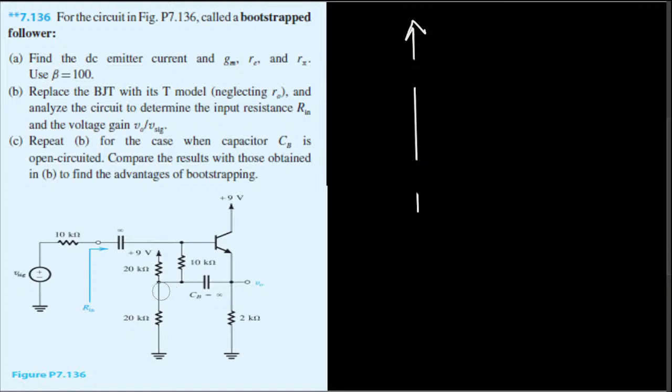Okay, we are drawing this 20k ohm resistor, and the bottom part of it is connected to the ground. This is 20k, and we are getting rid of this. This is also an open circuit, whatever the capacitor has. So it's going to be in series with the base right here. The 10k ohm resistor over there is in series with it, like this.